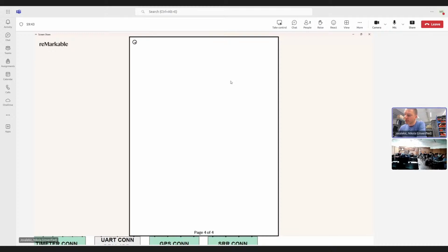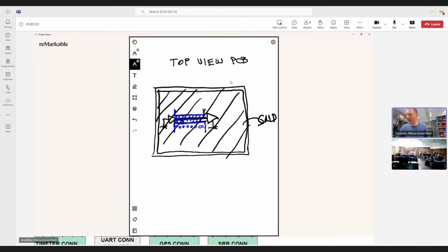So in order to just shield this, we will just put vias. That way, we will confine the field also vertically, I would say. So we will literally have, let's call it, a semi-Faraday cage. Because on the bottom layer, you will also have the ground.